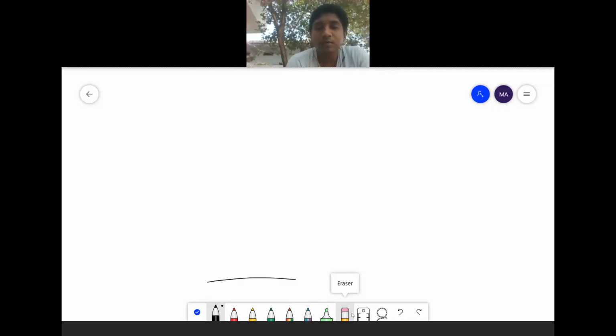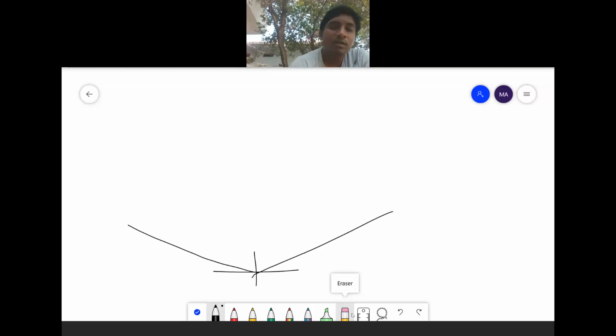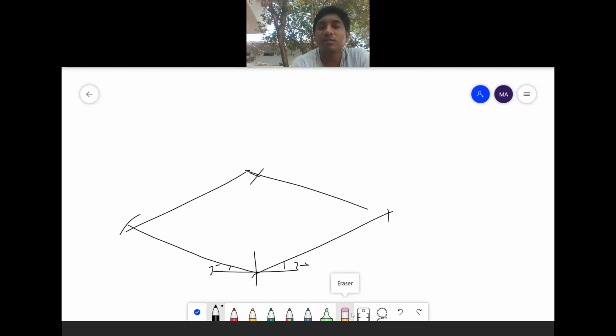So I am taking a line like this. I am taking 80, 30 degrees first. 30 degrees this side, 30 degrees this side. Cutting 80 here, cutting 80 here. I am marking the center points. I am drawing the circle here using the 4 center method.